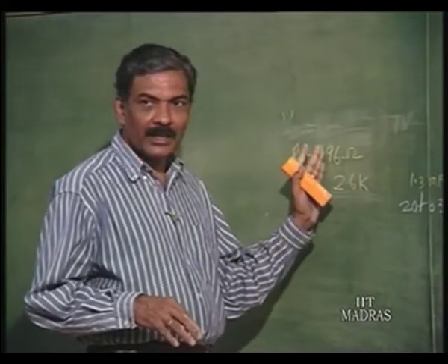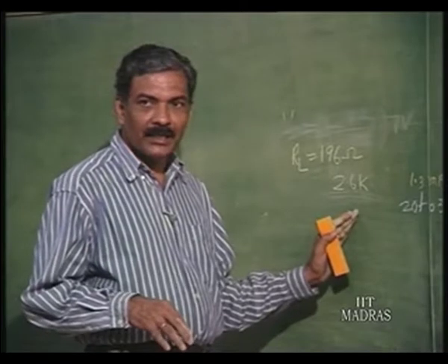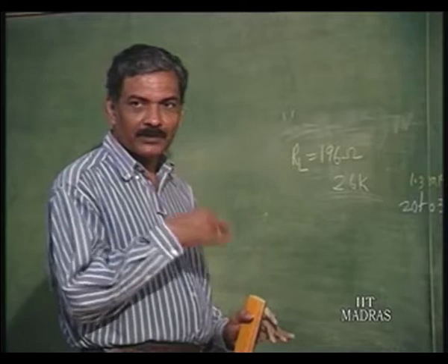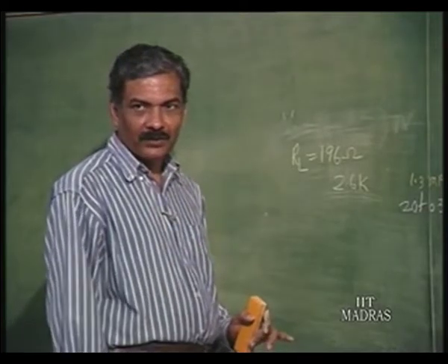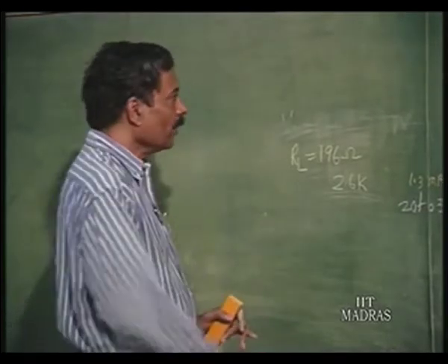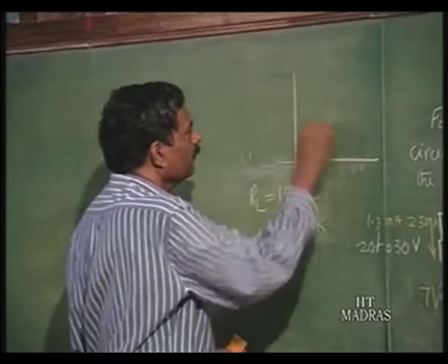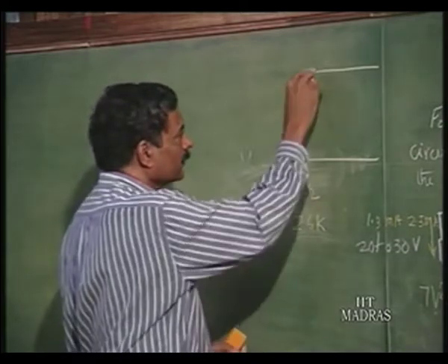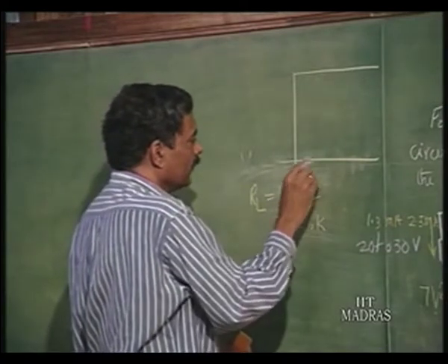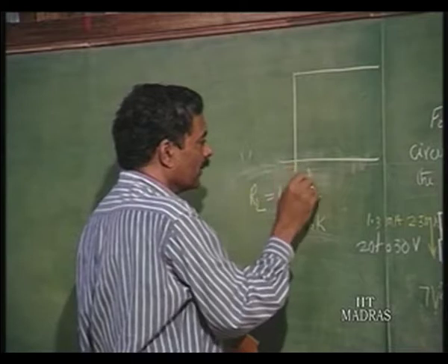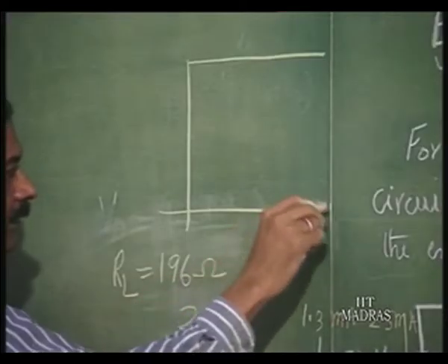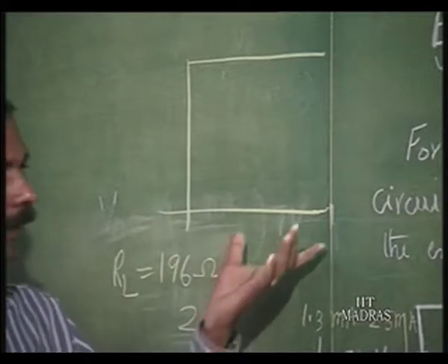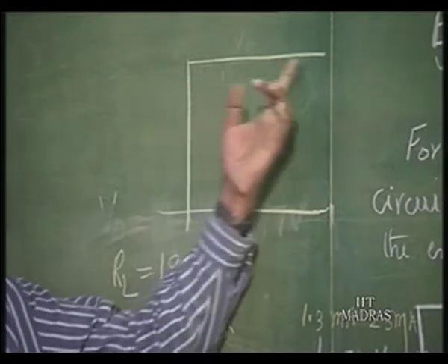Vary the load from 196 ohms to 2.6 K and find out how output voltage varies with respect to this variation of load. Okay. So, you can plot that characteristic, which will be looking almost as 14 volts constant, right. This load current is changed from, let us say, corresponding to RL equal to 196 to this is the maximum current, this is the minimum current, right. So, this variation you have to plot.